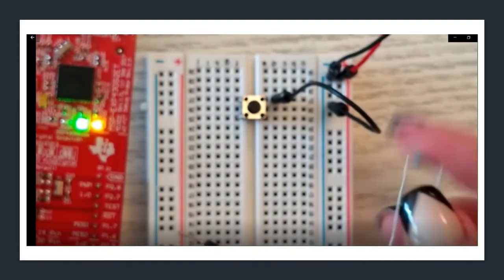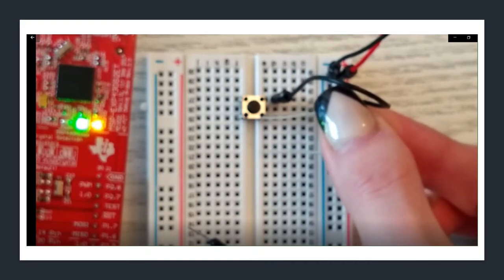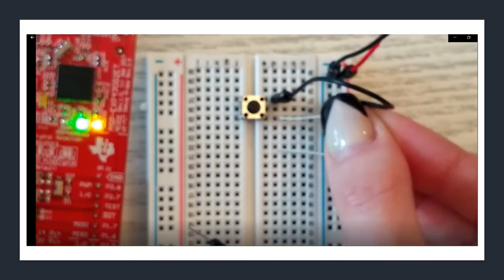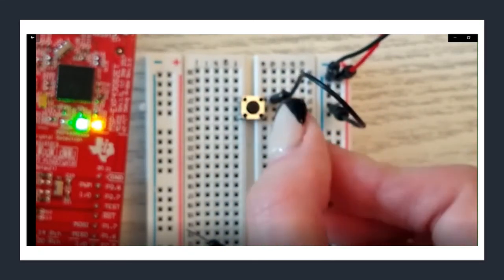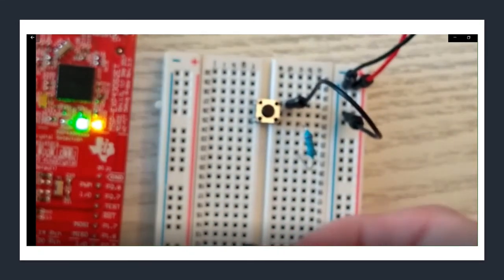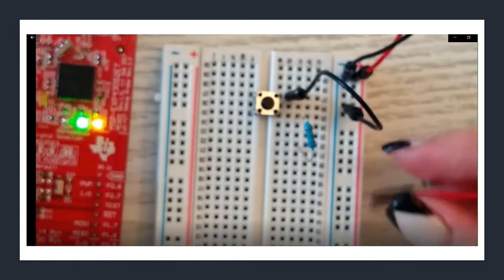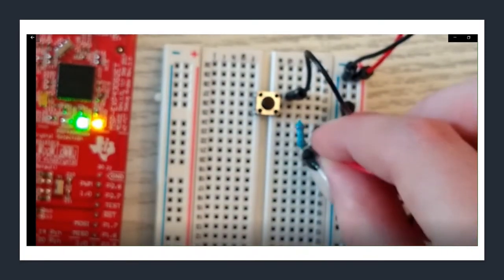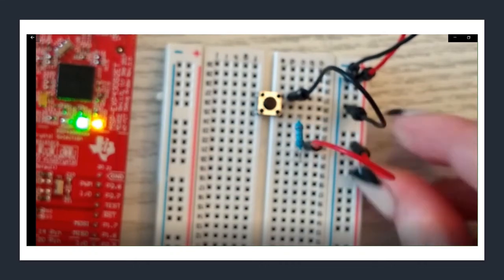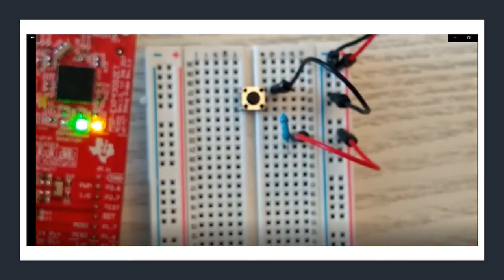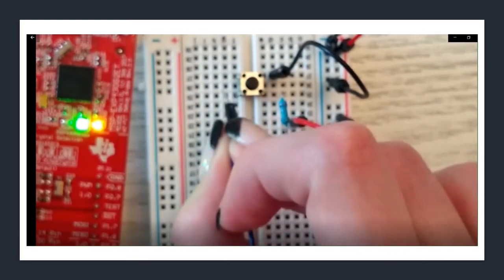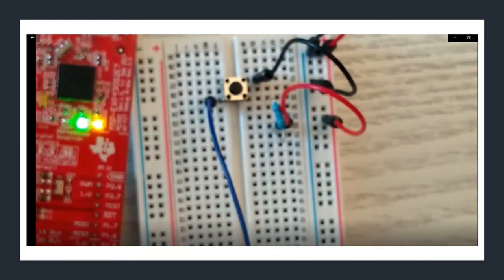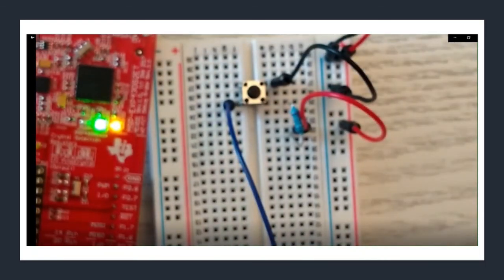So I'm just going to pop in a little resistor, in line with one of those corners of the push button. Sometimes these components can be kind of hard to put in the board, so just wiggle it around a little bit and make sure it's clicked in there. So I have that resistor on one corner of my push button, and then I'm adding power on the other end of the resistor. I'm plugging it into the power strip alongside of the board. And then lastly, I'll be adding a wire to the third corner of the push button, and this will connect to my pin, my actual pin number.